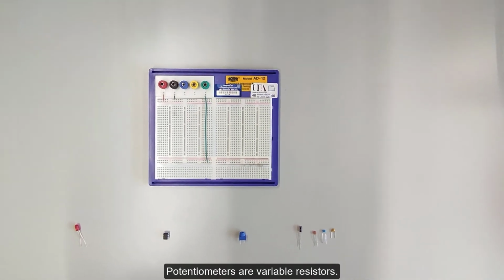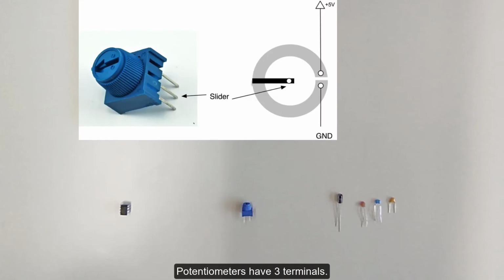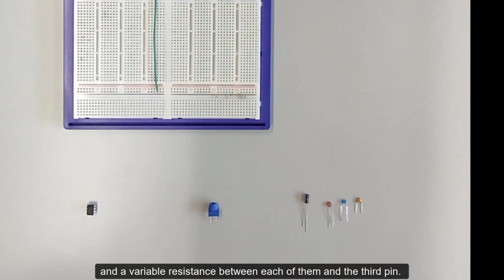Potentiometers are variable resistors. They allow you to modify the resistance by rotating the knob. Potentiometers have 3 terminals. They have a fixed resistance between these 2 pins and a variable resistance between each of them and the 3rd pin.